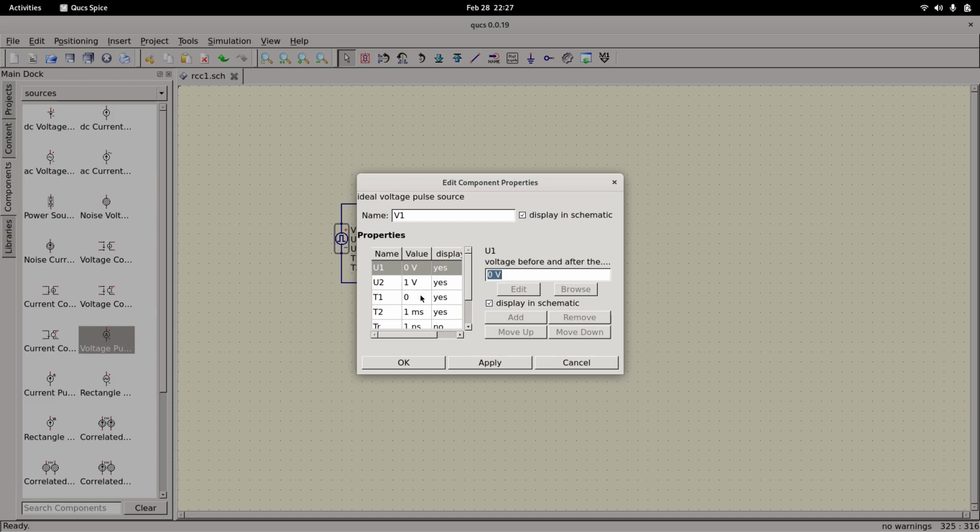Such a signal is required. So we will use a strategy that the on time of the pulse, the duration for which the pulse value remains high, is made much higher than 5 times the time constant. We know after 5 time constants circuit becomes stable.